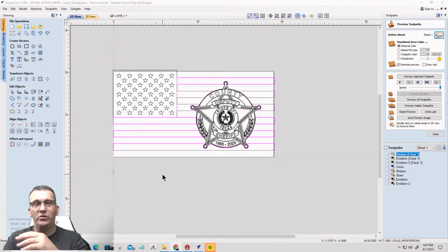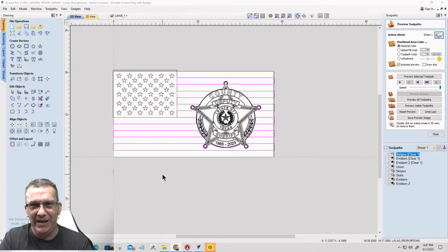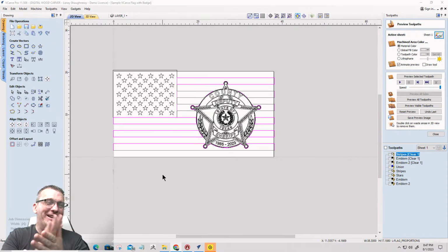No. Your commercial units, sure, you can go as big as you need. But hobby units and all, just not enough. There's not enough mass or construction to turn a big bit, anything over 2 inches. Just don't do it. It's dangerous. It's crazy.